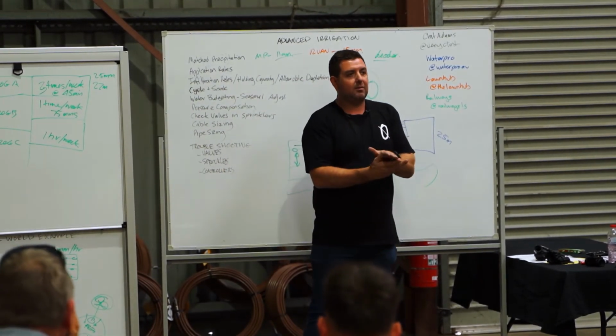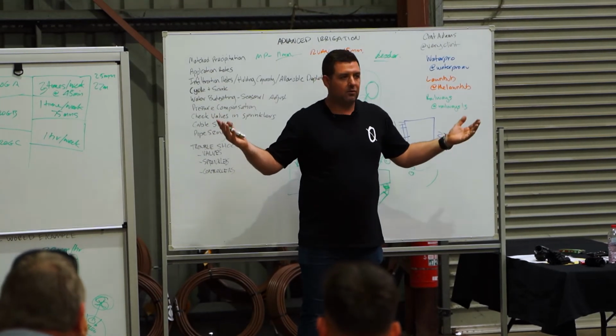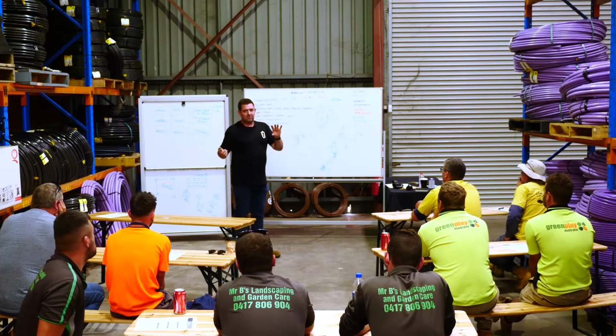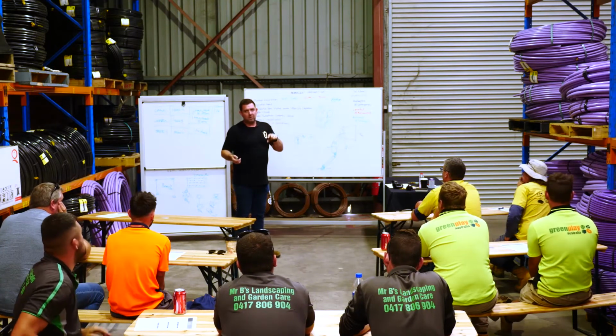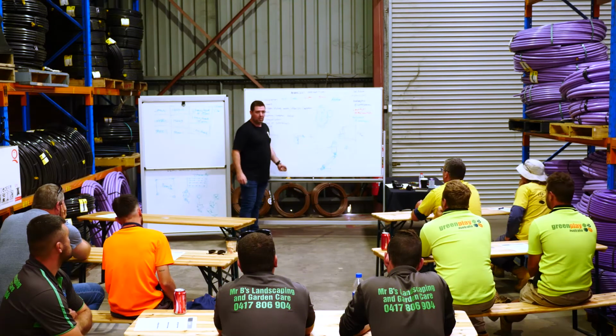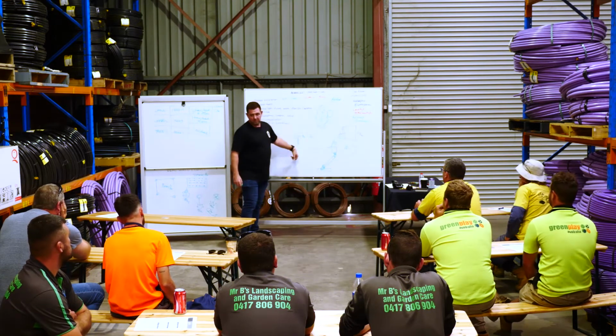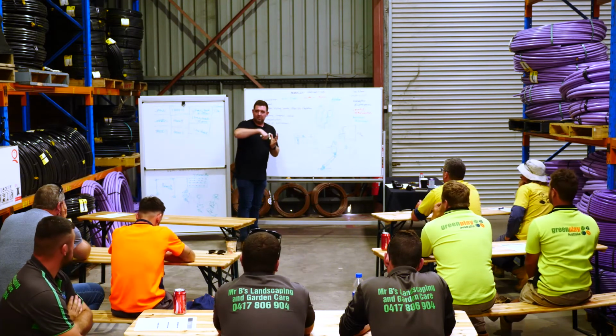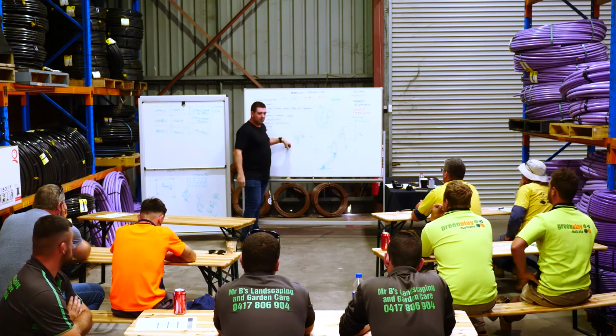19 mil, you've probably done MP rotator systems hundreds of times off 19 mil with no issues. If you start going above that 30 liters a minute, it's worth looking at 25 mil. If you're doing drip systems like this, where you're actually punching the header pipe, the 25 mil is going to be better anyway, because it's easier. You're not getting that rounding where it's hard to get a clean punch.